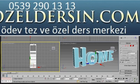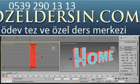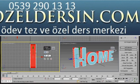Then we'll select the Polygon mode. We're going to drag the cursor right through the center. So we just select the center polygons. Now we're going to come over to the Edit Polygon panel and select the small settings box for Inset. And now we're just going to type in 1.5 and then press OK. Just press OK twice. I think we might do another inset, so we'll click again on the small settings box. And this time we're going to type in 0.5 and then OK.